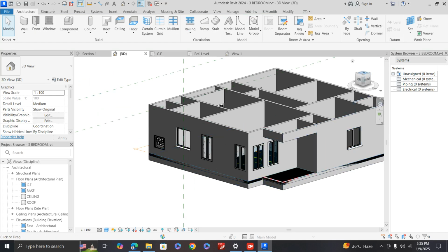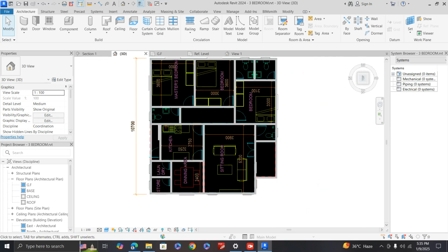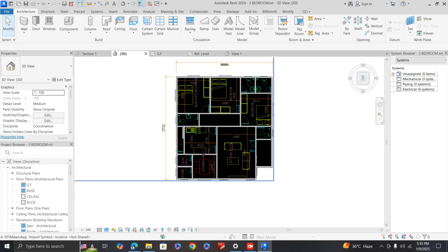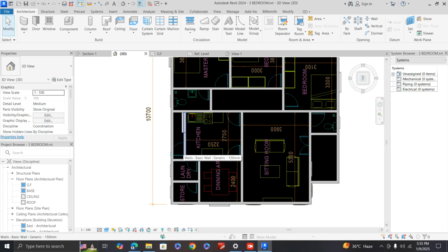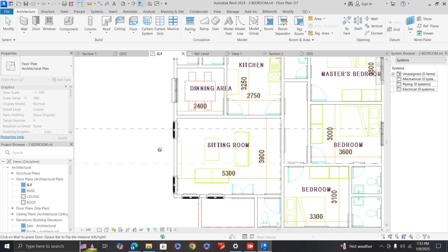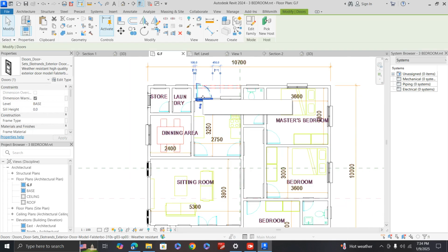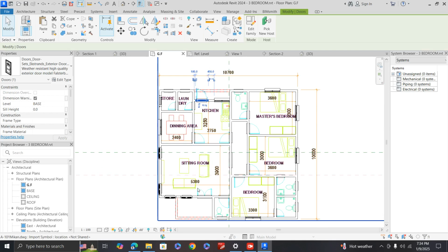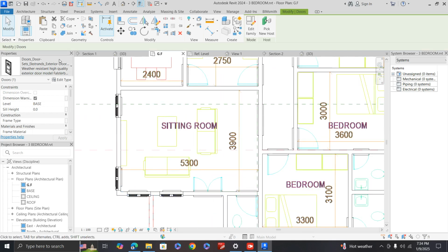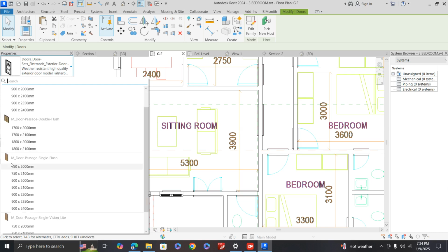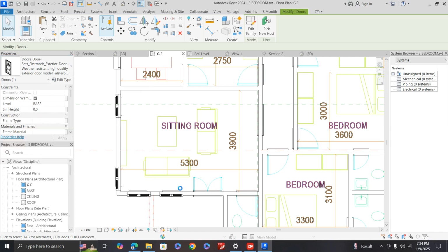So let's work on the doors. I've downloaded some doors as well: the double door for the main entrance, the single doors for the restroom, and the exit door here, which is going to be a metal door, an external security door. So I'll start to place some doors. I downloaded one for this exit door right here. Good. Then I need a double door right here, but I can make use of those flush doors here for restrooms. I prefer 900 by 2.1 meters for the interior doors.